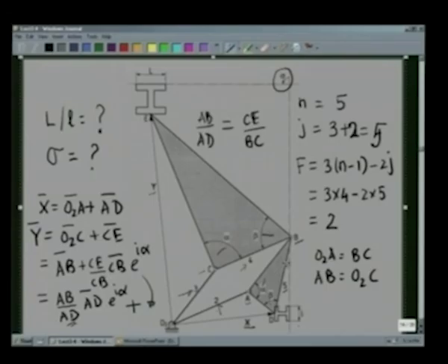Not only that, this vertical side, which is vertical like this, has been oriented through an angle sigma, and we have already shown that sigma is nothing but the angle alpha. So, this is the copying mechanism, that any arbitrary figure drawn by the point B or followed by the point D can be reproduced at the point E at a different size and different orientation.